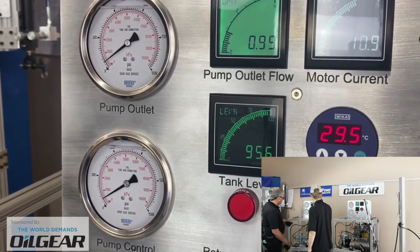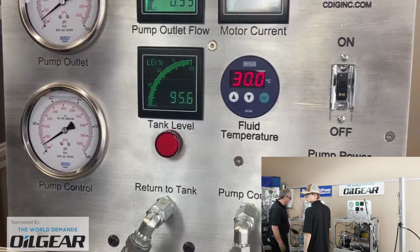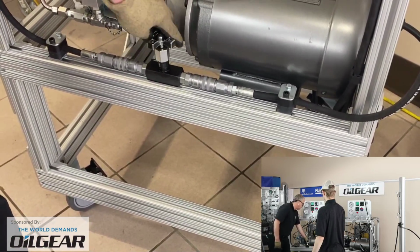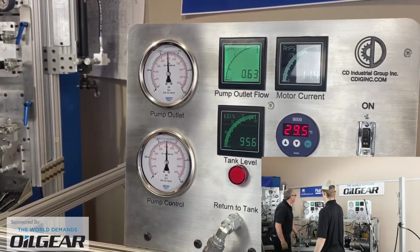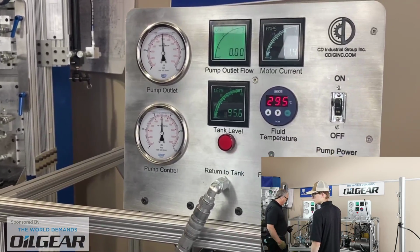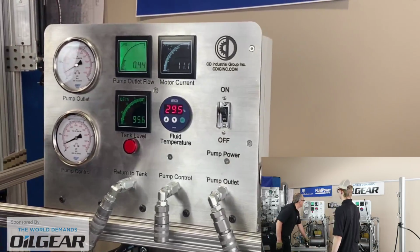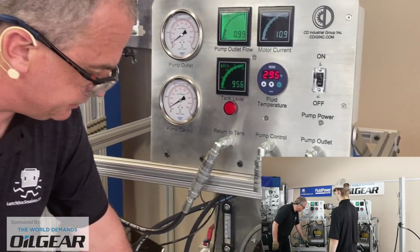Okay, so there we are. We have adjusted both the pressure compensate and the flow rate. Our flow rate is now at about 1 gallon a minute. If I shut the flow rate back in, our pressure compensate value should not have changed. That should be about 750. Those two settings are largely separate from each other, independent, as long as you did them at a similar time when the oil was at a nominal level required for making the correct adjustments.